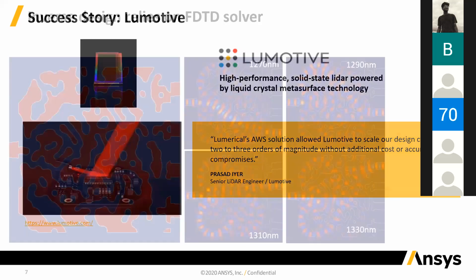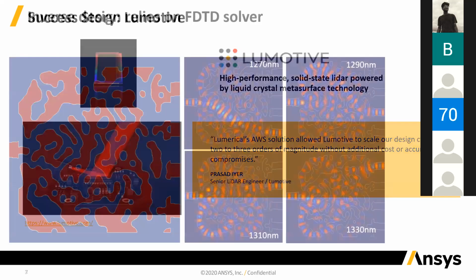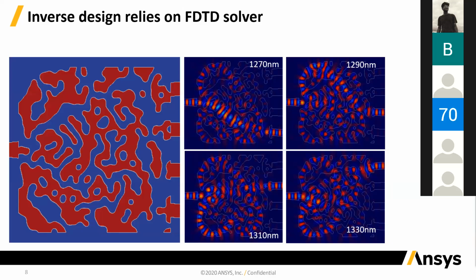Another cool feature of FDTD that I thought would be very interesting to the audience here is called inverse design. This is an optimization technology, and it is more relevant to people who are interested in photonic integrated circuits. When you want to work with a photonic integrated circuit, it comes with lots of different building blocks. And so you have to design all of those individual building blocks manually most of the time. With inverse design, you can actually automate that process.